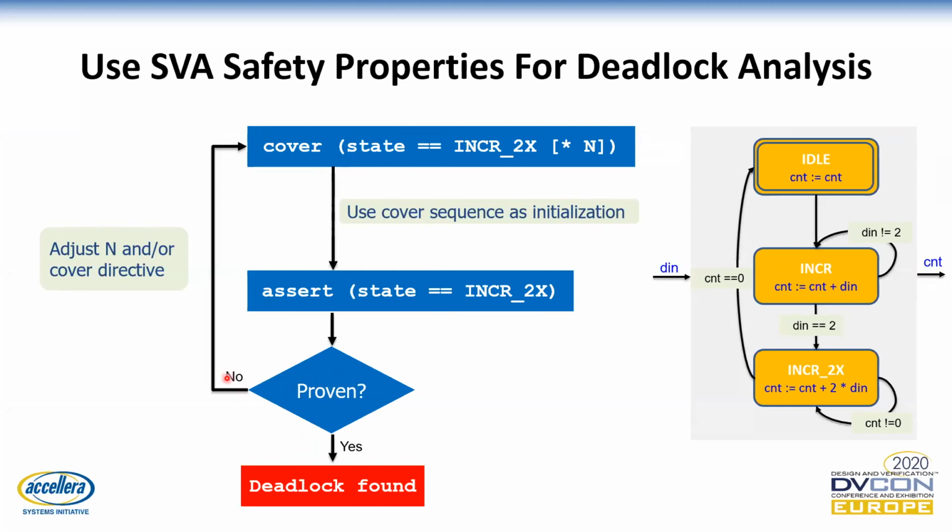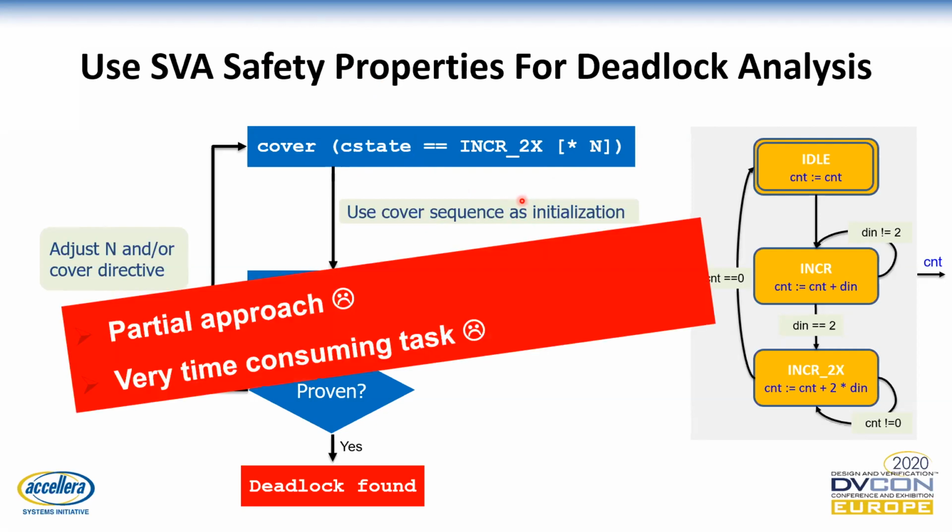Otherwise, we don't have a deadlock, and then we have to go back and maybe adjust our initialization by modifying this cover directive, adding some signals or changing the delay here. So this is something that can be used, but it's actually also partial and very time consuming.